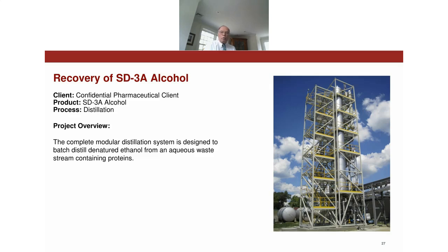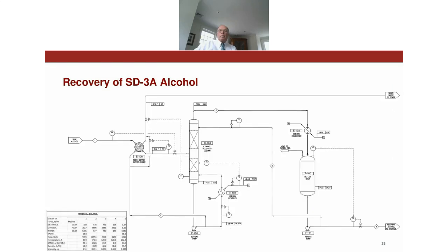And the client's goal in this application was to recover a denatured alcohol that was approximately just shy of 94 weight% alcohol. So the 94 weight% is the combined ethanol and methanol in that stream. So that was their goal for a recovered solvent, and the bottoms of the column was wastewater.